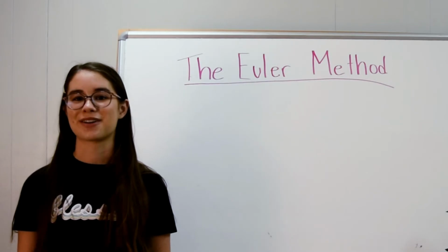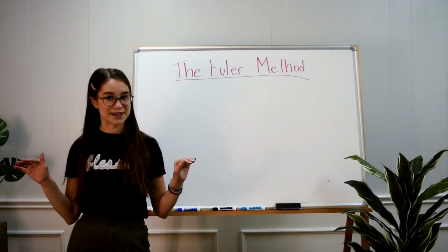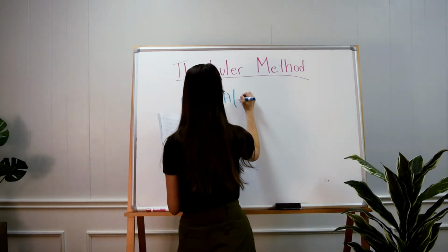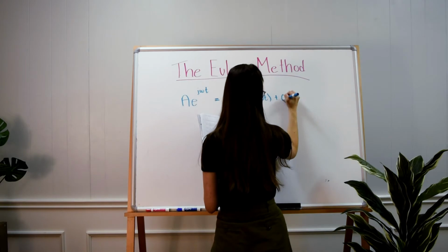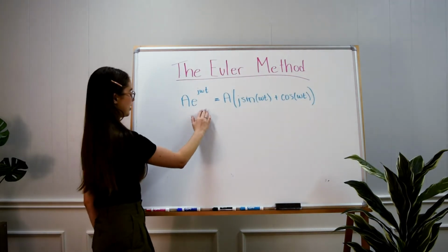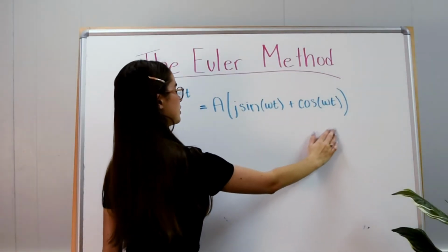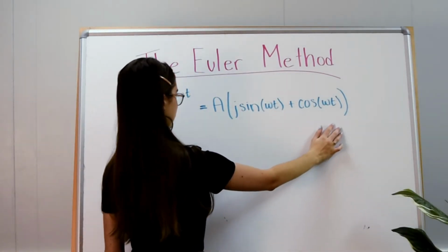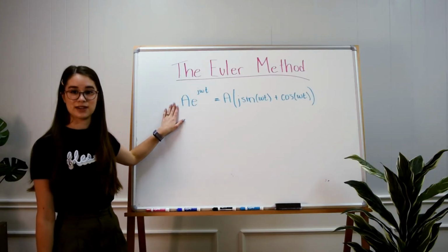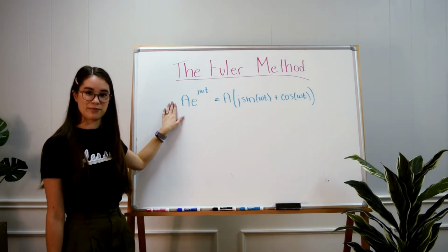Alright, let's talk about our good homie Euler. He's got this thing called the Euler Identity, and here we're going to be using it to be converting between polar and rectangular coordinates in the complex plane. So in this equation, the e to the j omega t piece is our complex vector that is denoted using sine and cosine. Using this, we can find the magnitude of A to find the amplitude of the output, and the angle of A to find the phase shift of the output.